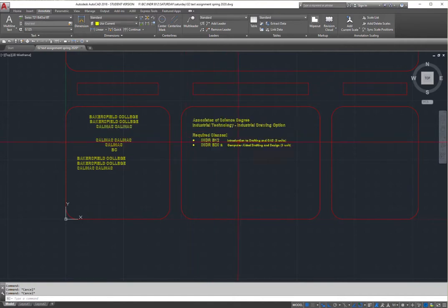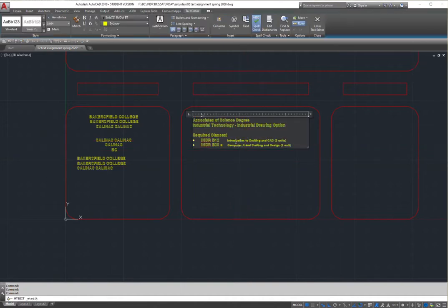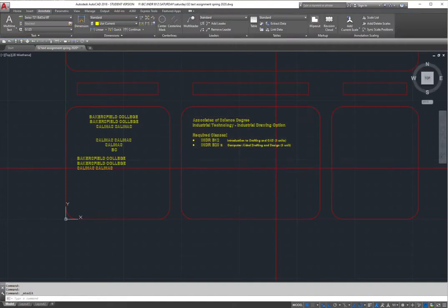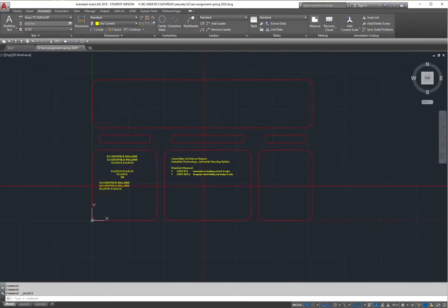If I go here with my multi-line text, it becomes a single unit, so I have to go in and I can modify everything inside, and it automatically gives me the modification tools right here that I need to do whatever is needed. Okay, so that's my multi-line text. Now, since we are right here, and I think we have a little bit of time in this video,